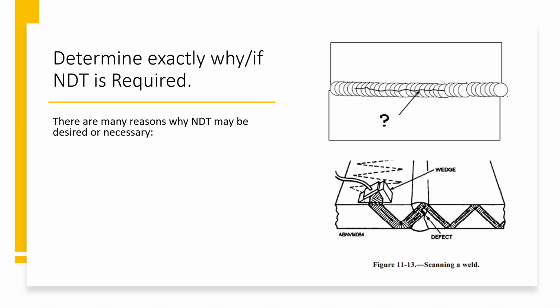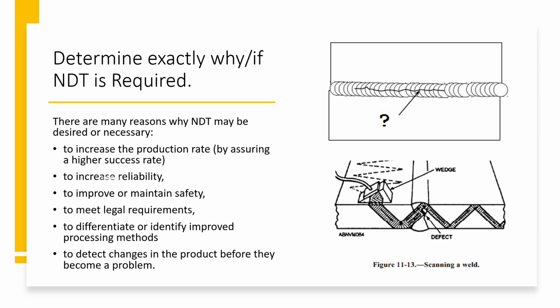So here are some reasons why NDT might be desired or necessary. Increasing the production rate by getting a higher success rate. Increase reliability, improve or maintain safety. That's a big one. To meet legal requirements. Okay, we're building a boiler. It says we have to have this much non-destructive testing on this thing so it doesn't blow sky high.